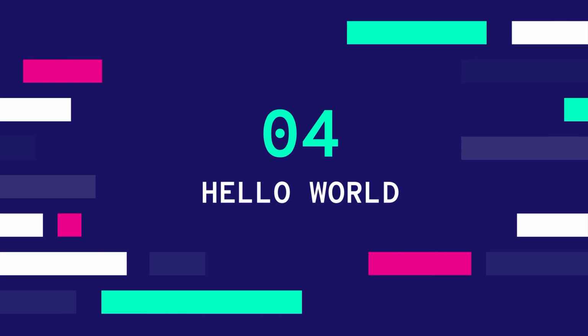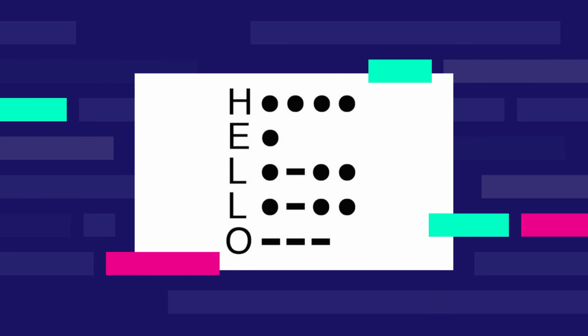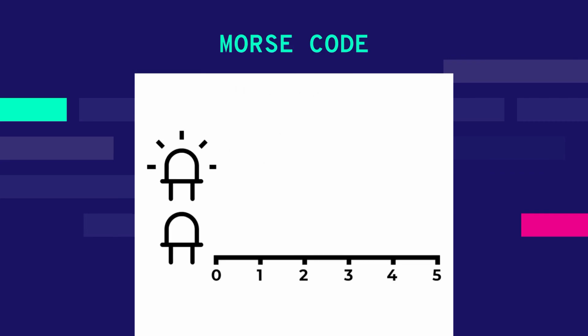Let's see if we can take this a step further by getting the Arduino to say hello using Morse code. Morse code is a way of encoding text using a sequence of dots and dashes. Each letter has its own sequence. By flashing the Arduino LED in the right way, we can make it spell out words. It's important in Morse code to make sure that the dots and dashes are sent using a fixed time unit. A dot will light the LED for 1 time unit. A dash will light the LED for 3 time units.